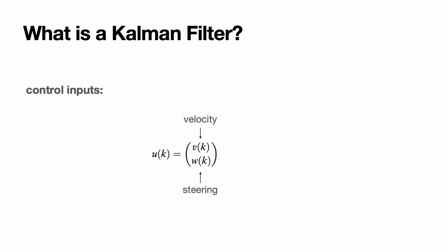The state vector described here now only includes the rover position and heading. If we want to describe the whole system, we should not only store this state vector, but also all the landmarks that have been seen by some LiDAR sensor or any other optical payload.